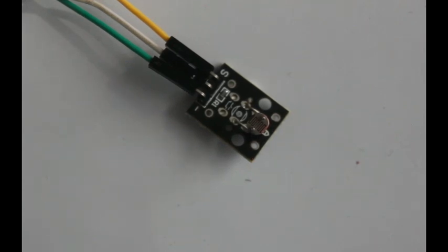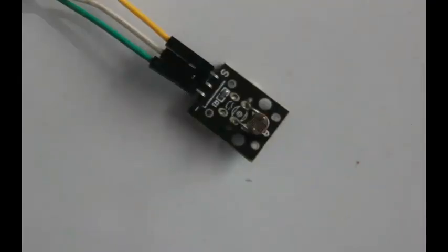Now that we know what a photoresistor is, we will look at the working principles of a photoresistor, and they are as follows. The first thing is the semiconductor material. Photoresistors are made from a semiconductor material, typically cadmium sulfide, which exhibits high resistance in the absence of light and low resistance when exposed to light. We will see this when we look at a practical example whereby we interface the photoresistor you see in front of you with an Arduino Uno.